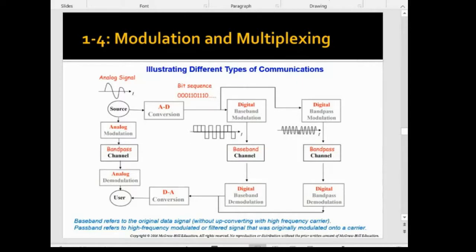So we modulate messages or transmitting signals with a high frequency carrier, and then we can send by an antenna and we can receive by an antenna. So then the antenna can be a smaller size. So that is one of the main reasons.